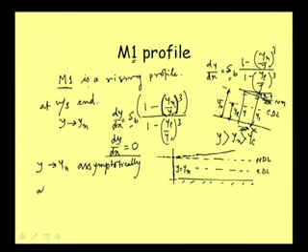Well, then at the downstream point what will happen? It is rising like this, then to what extent will it keep on rising? In fact, when we get the M1 profile, it is above normal depth.